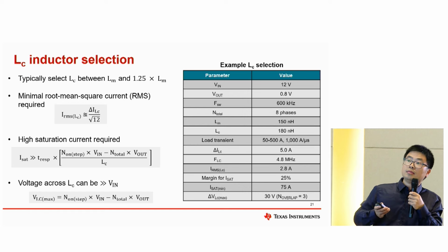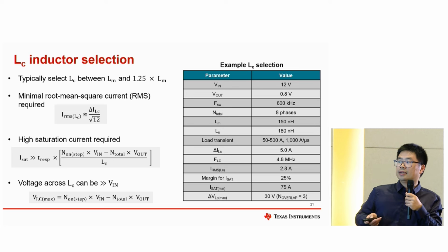We select this from the beginning, and then adjust the value of the LC inductance according to the efficiency and the load transient performance.